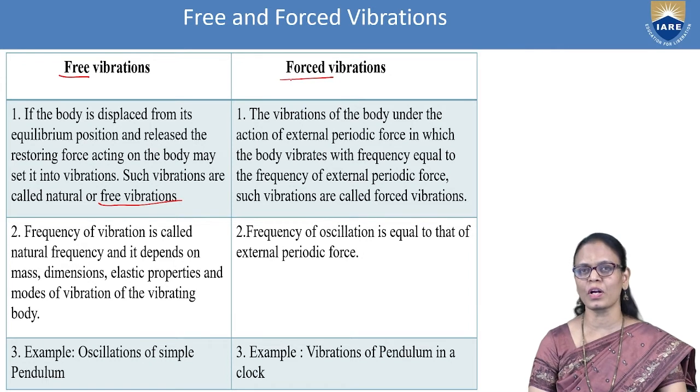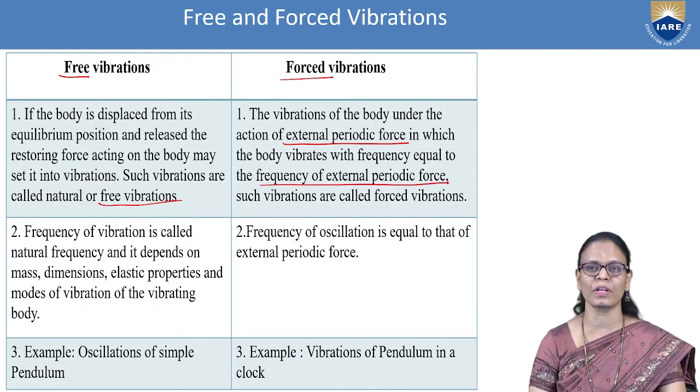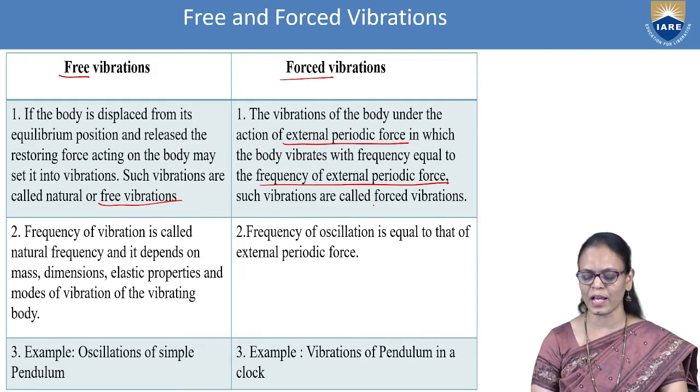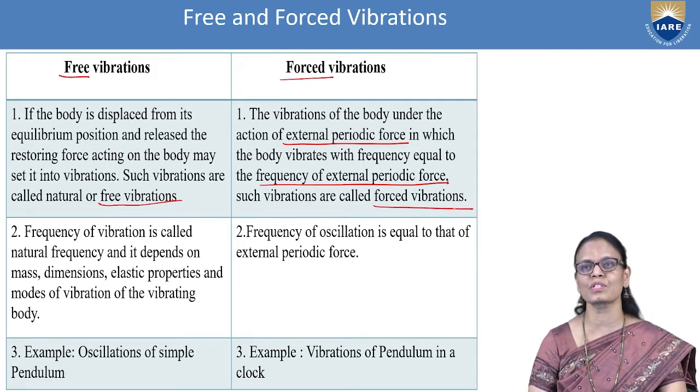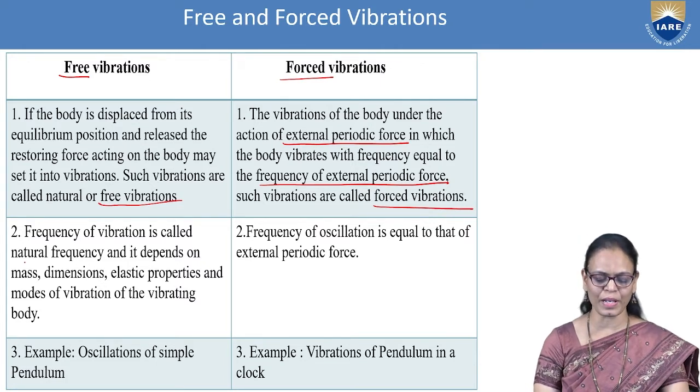Now, in forced vibrations, the vibrations are under the action of an external periodic force, in which the body vibrates with a frequency equal to the frequency of the external periodic force. They are not oscillating with the natural frequency, but the vibrations depend upon the external frequency we are applying. Such vibrations we call forced vibrations.